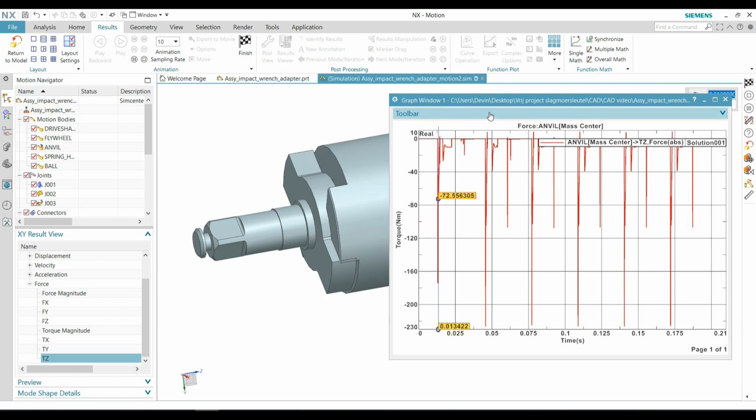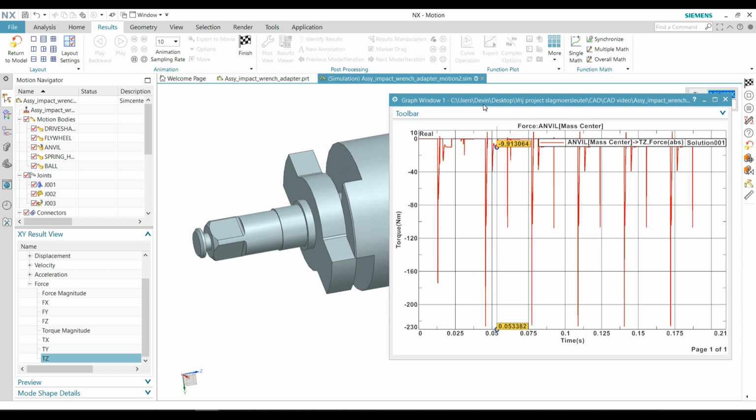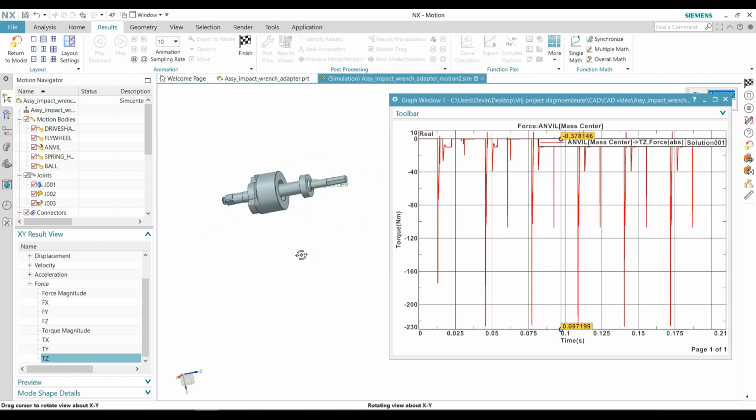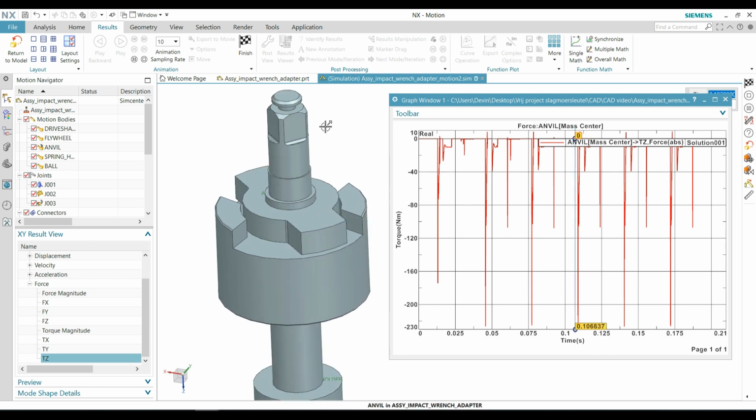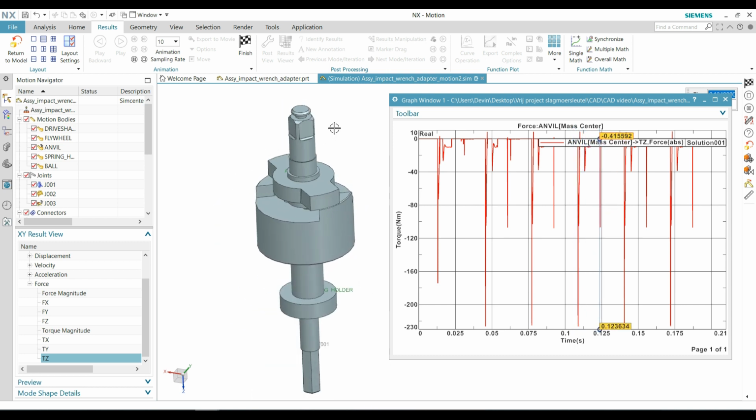Loads that are obtained from the dynamical simulation can be used as input for FEA strength analysis. The main concerns to analyze would be the contact stresses in the V-grooves and the surface between the hammer and anvil. This has not been done for this particular project, since we are making a prototype and do not have hardened steel with the desired properties anyway. In case of production for actual use, FEA should be done to evaluate wear and lifespan.